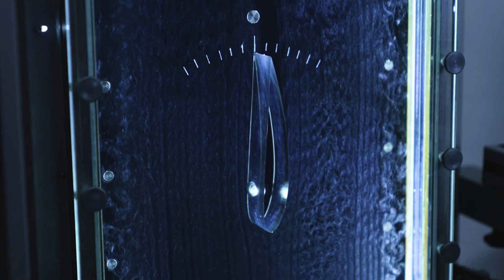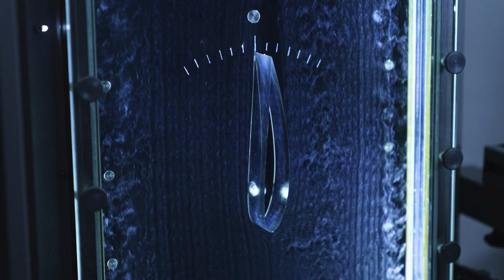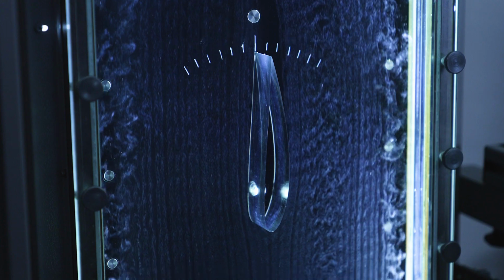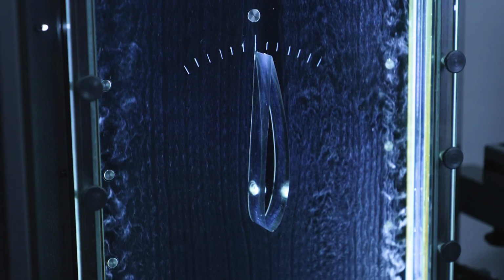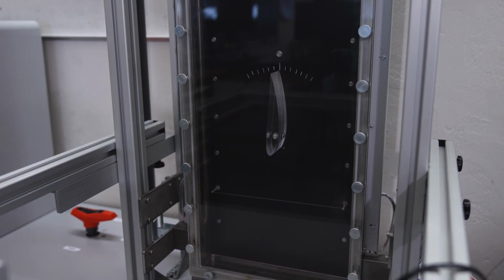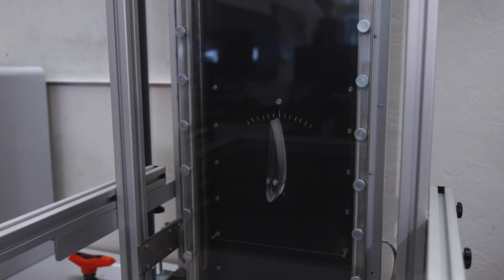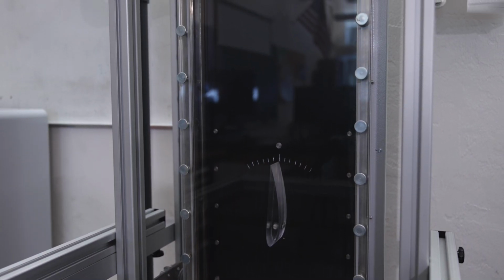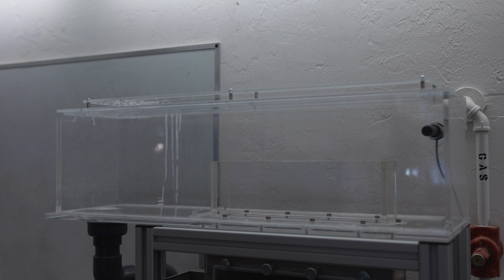The bubble generator consists of a DC electrical system that passes a current through a platinum wire. The wire extends across the test region and seeds the flow with hydrogen bubbles created by electrolysis. The bubbles follow the fluid path, displaying the fluid flow field. The test region is where models are affixed and the flow fields are visualized. The dimensions of the test region are 860 millimeters in height, 300 millimeters wide, and 49 millimeters depth. The degassing tank helps remove the bubbles pumped by the system.